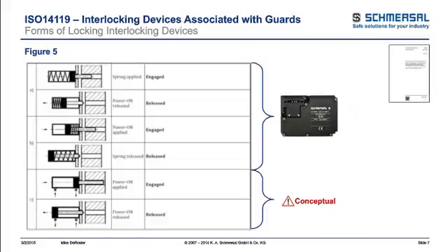Now, when we look at locking, one of the questions that have always come up is, as a safety consideration, should we use energized to lock, or should we use energized to unlock? What is the true safety definition? What is the safer? No matter what you come up with, it really does come up to your full risk assessment to determine the proper use of a locking device. But the statement, I cannot use a power to lock as it's not allowed in a safety system, is not true.